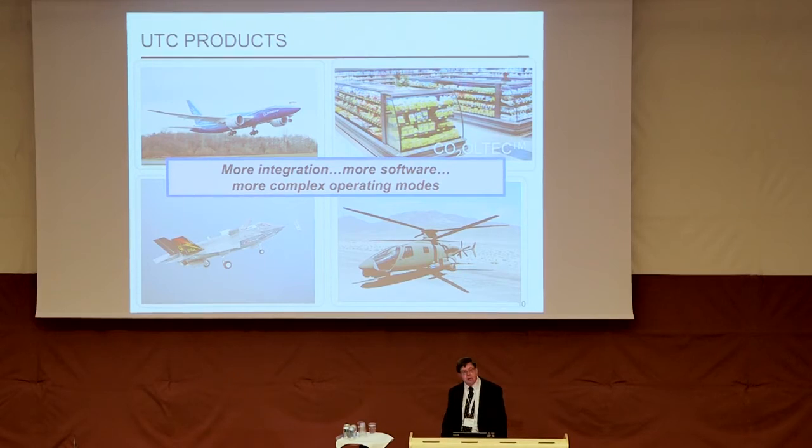So this is a quote-unquote more electric aircraft. We'll talk about what that means a little bit later, but from a commercial perspective, this aircraft compared to comparable aircraft in its size range is 30% more efficient. Years ago, for those of you who may have gotten here by plane, energy was effectively zero cost. Other cost structures affected the aircraft industry. Today, about 60% of the operating cost of an airline is fuel. And so if your plane is 30% more efficient, you're going to have a competitive edge. This is really due to 2 things. It's more electric, it's also composite, so it's lower weight.